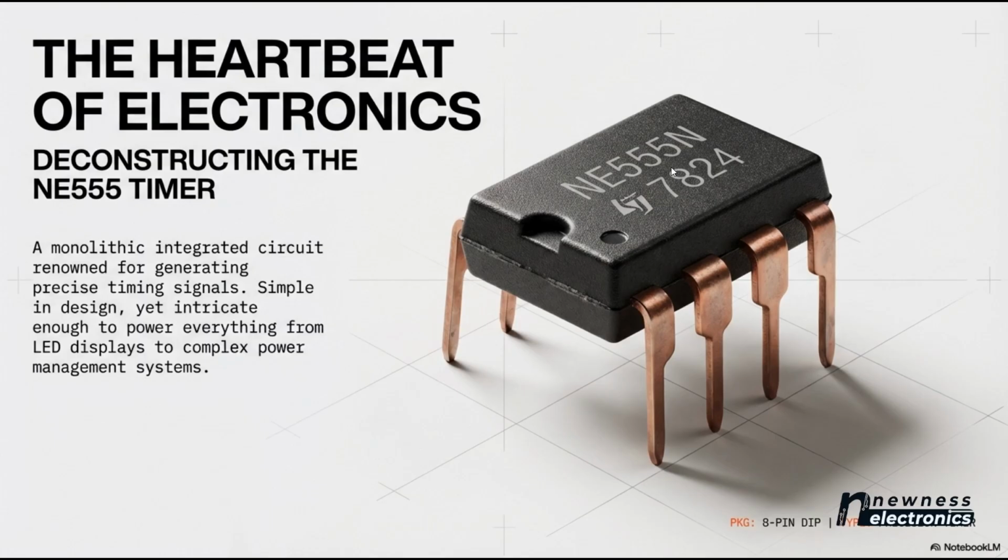If it's a 3-pin component, it may be an IC, it may not be. For example, the LM7805 is a voltage regulator IC, but the TIP41 is a transistor, yet the two of them are 3-pin and the same package. So if it is 3-pin and you are not sure what it is, Google search it. Or if it is 4-pin, you can also Google search it. Sometimes 4-pin can mean a bridge rectifier diode.